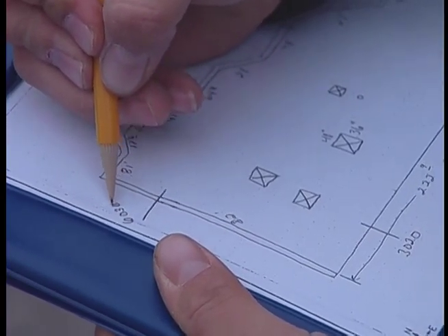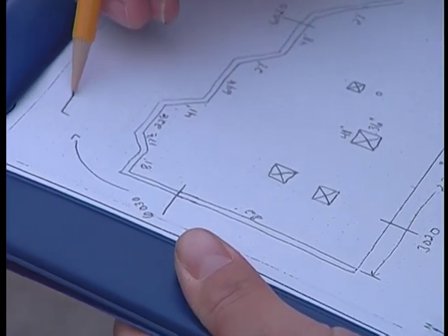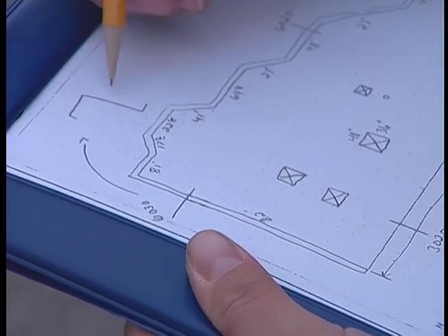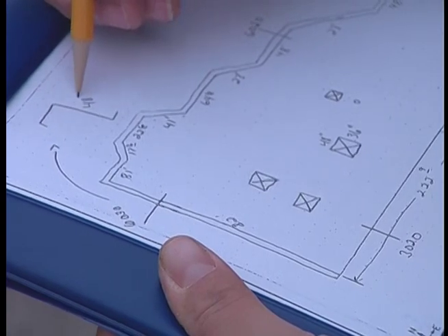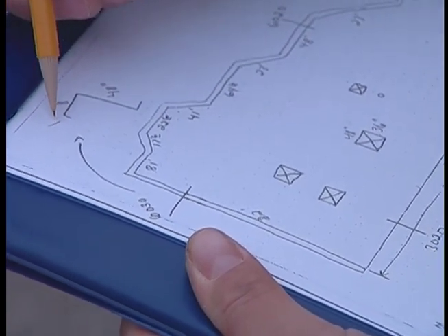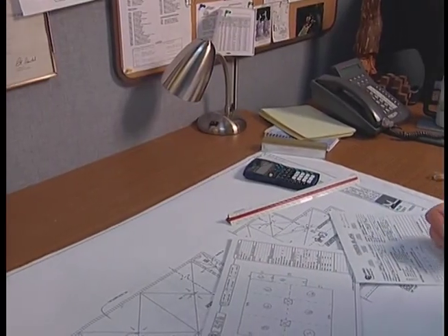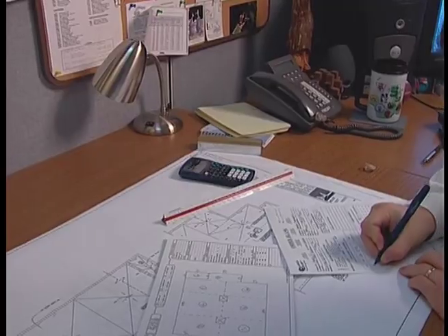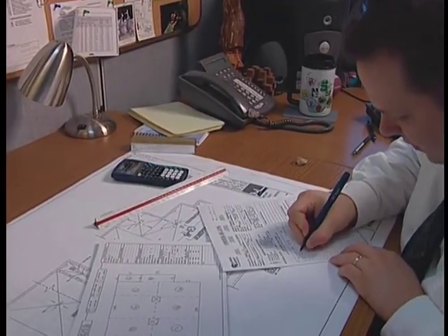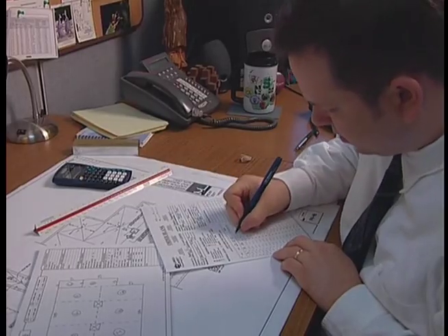Remember, deck sheets and parapet sheets are ordered separately and manufactured differently. By keeping these measurements separate, you're keeping all dimensions organized. This is important in the layout procedure so that you'll know the square footage of the deck and the square footage of the parapet walls. The Duro-Last order blank offers a complete list of Duro-Last accessories. Review this list carefully to ensure that you select the accessories you'll need for your job.